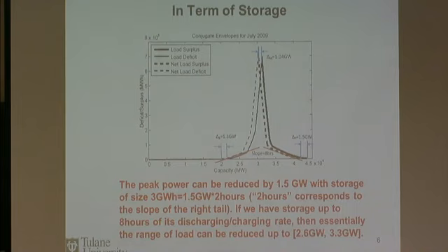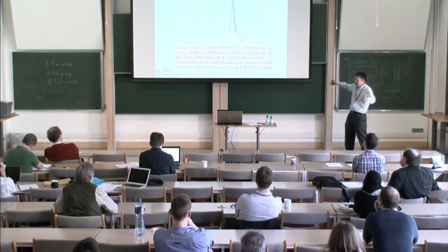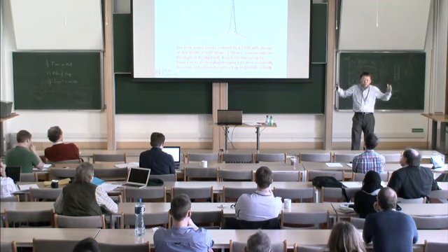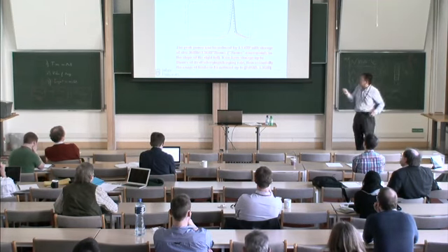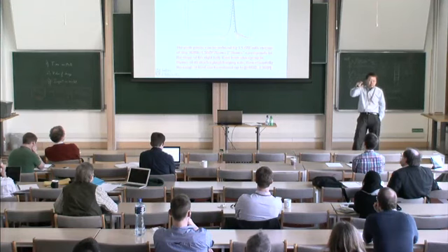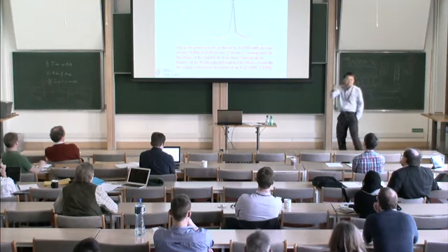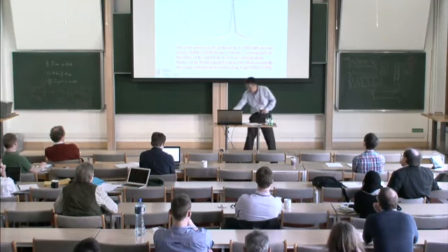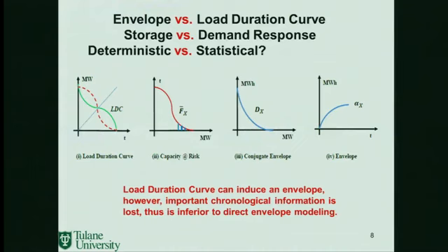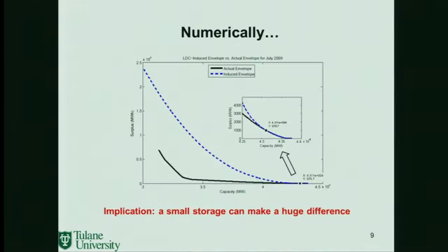So the most important thing is this red line. You see the slope is in units of hours. Basically, I can shrink the whole capacity, and smooth the power by a significant amount, as long as I have storage, in a sense ideal storage, with a size of 8 hours, the ratio between the energy content and the power capacity. And also, if you look at the tail side, it is actually not 8 hours, it's 2 hours.